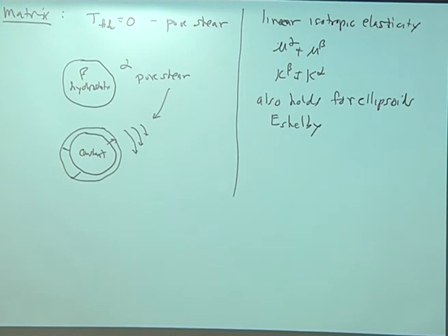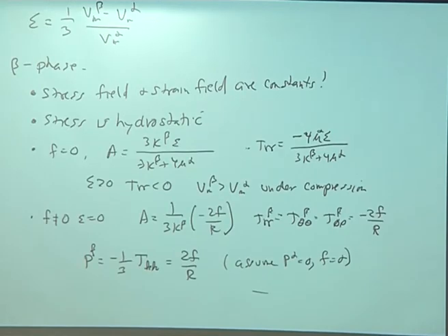So this is an interesting sidelight. If you think about the thermodynamics of fluids, it is always associated with pressures, PDV terms. Here you have a matrix that's under pure shear that clearly has energy associated with it, but it's not PDV energy. It's strictly the shear energy. So you have to do the full elasticity, the full elastic energy, to get that right.